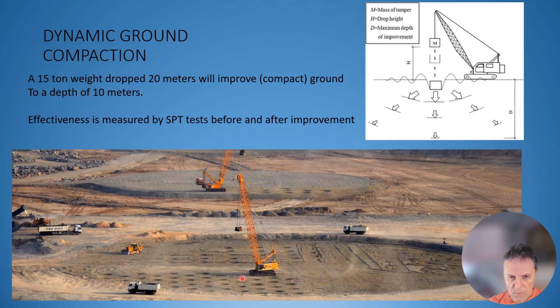So each one of these dark spots here is where this crane has been dropping the weight and compacting the soil below if you have a soft soil condition. Bam, bam, bam, bam. That compacts the soil. You have better foundation conditions. You want to test or measure if your method has worked by using standard penetration tests to get the relative density of soil before this procedure, and you want to do the same thing after the procedure to see whether indeed the soil has densified to the desired depth.